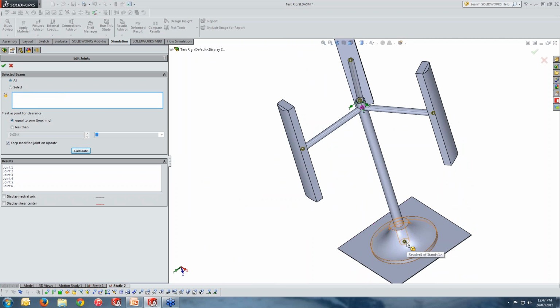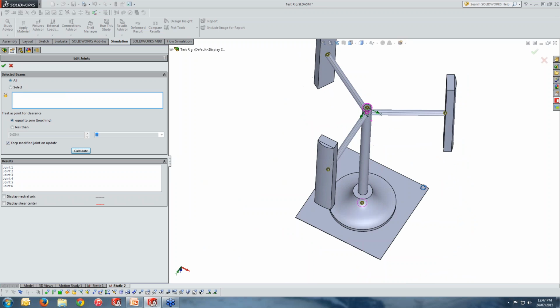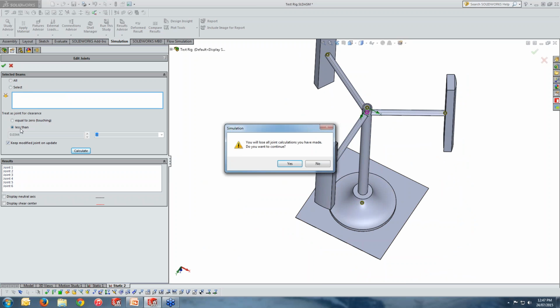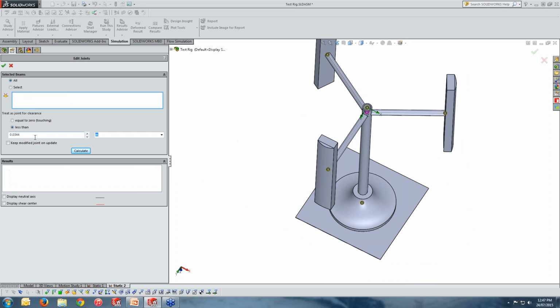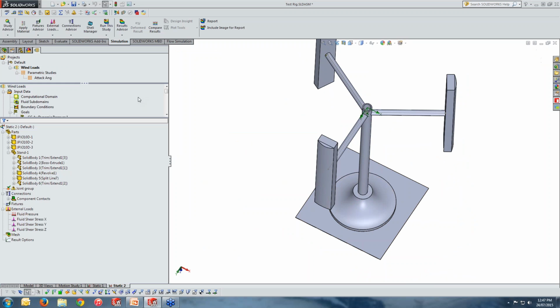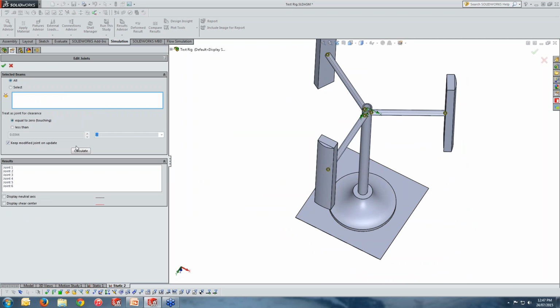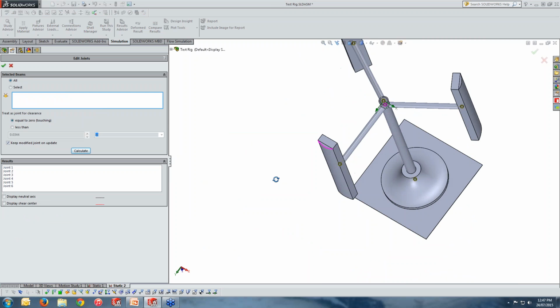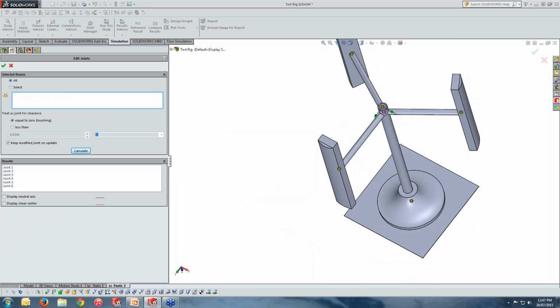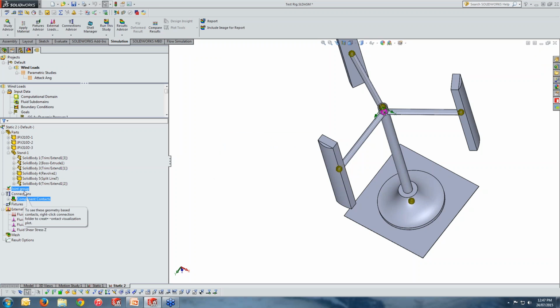and make sure you're creating enough joints as you might like. So point 1, point 2 represent the solid bar, and these 2 points are simply creating the next one. If you would like to make more or fewer joints, you can change these values. So let me cancel and re-edit the joint and say select all, calculate, and make sure all the joints are there, and it is simply the connection between the parameters as we have. Clicking OK, and I do have my joint group.